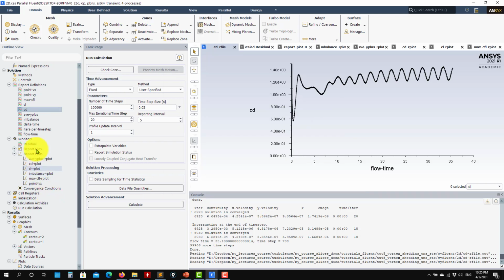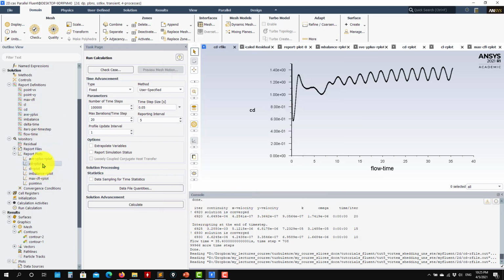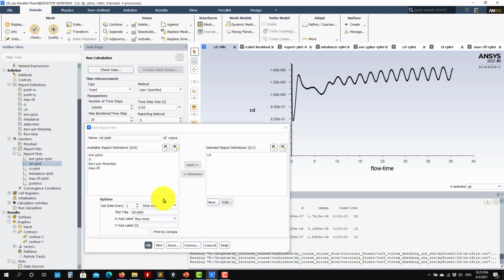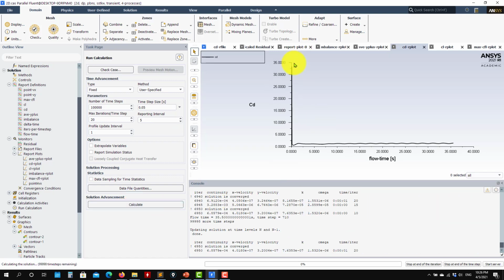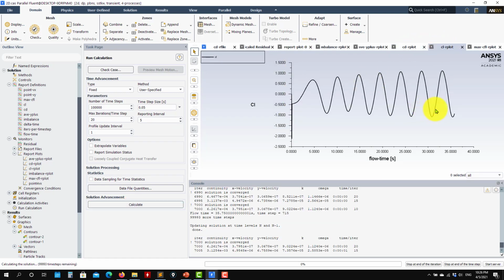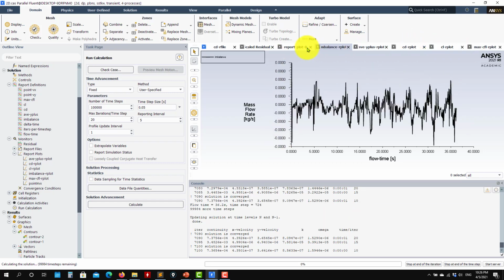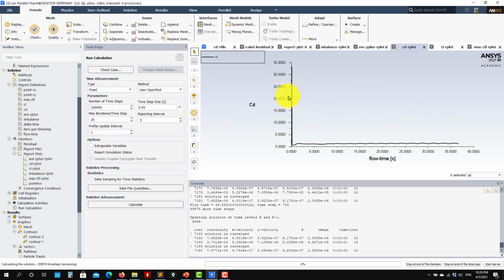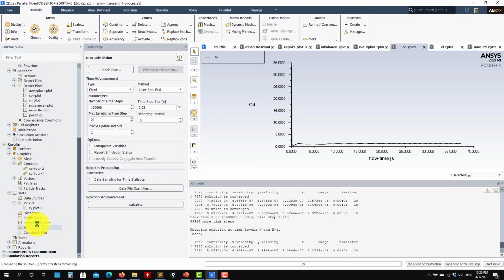The other thing that I would like to mention is when plotting these forces, let me go here and let me go to this plot. Axis and plot. Some people don't like this when you are running, and you see that you have this scale that is automatically chosen by Fluent in all these plots. But if you don't like this scale, the axis, the minimum and maximum, you have seen that it can be changed, as when we were doing the FFT.